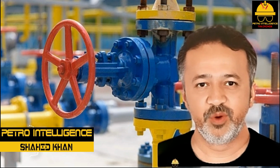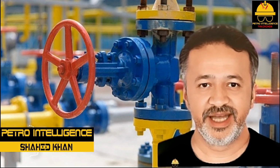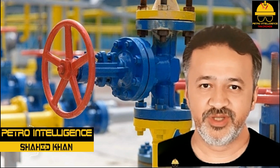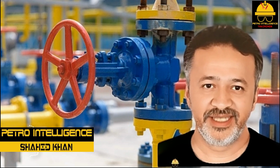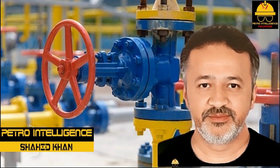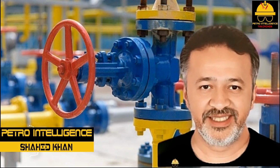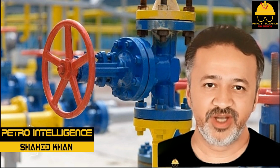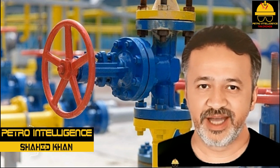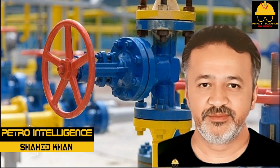Maintaining equipment is an important part of an operator's job. On gate valves, stem threads exposed to weather need to be lubricated. The packing should be inspected, and the gland nuts tightened evenly if a leak is found. Valve stems should not be painted, and every effort should be made to keep them free of dirt and dust. Process technicians should not over-tighten a gate valve, to avoid damaging the seats. When the gate is on the bottom, a wrench should never be used to wedge it closed.